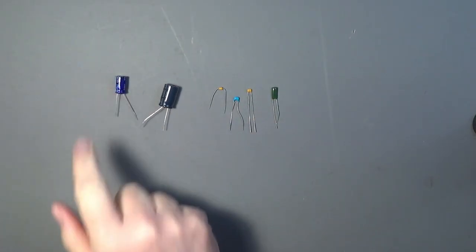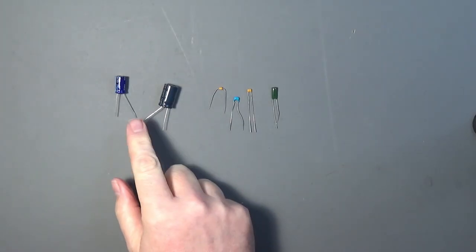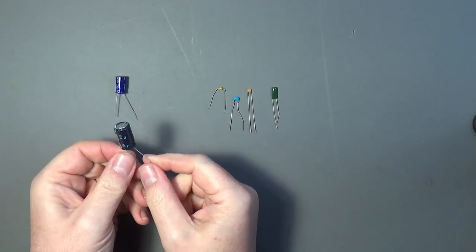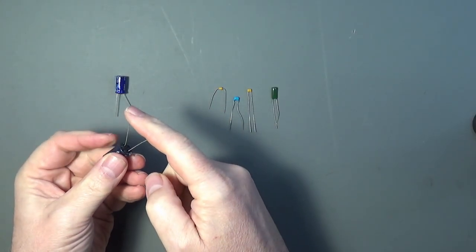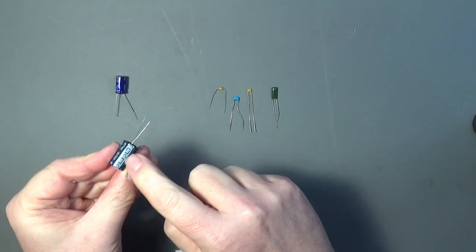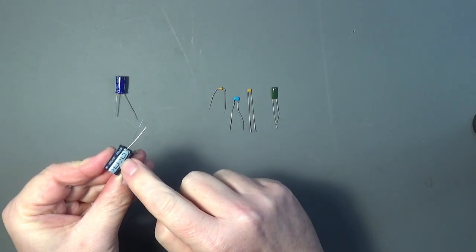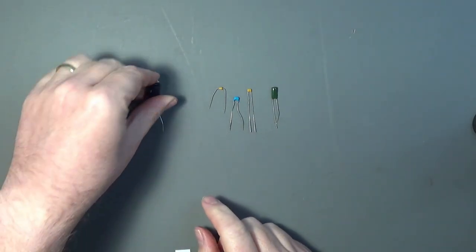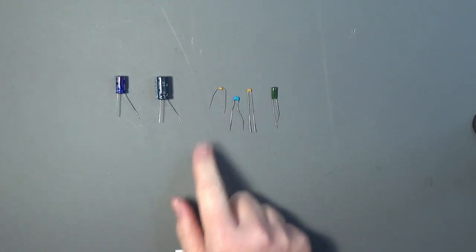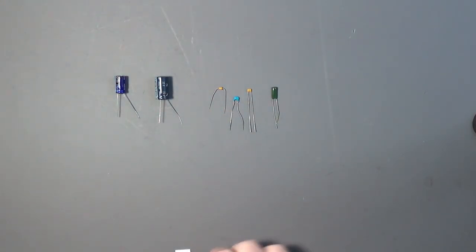These ones in cans are called electrolytic, and since these ones are polar, you have to actually put them in the circuit the right way. So the long lead is usually positive, the short lead is usually negative, and they usually mark the negative lead with a big white stripe like that with a minus on it. So it's usually pretty easy to figure it out. So those have to go in the circuit one particular way. These go in the circuit in many, many different ways.